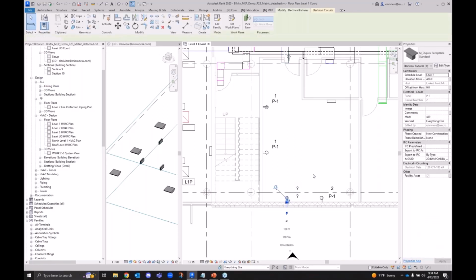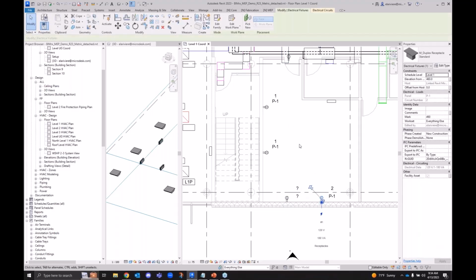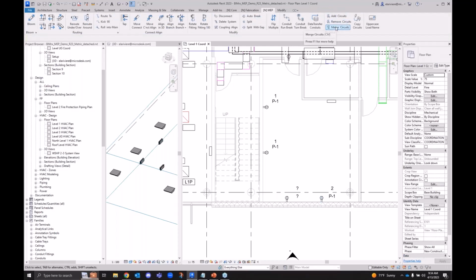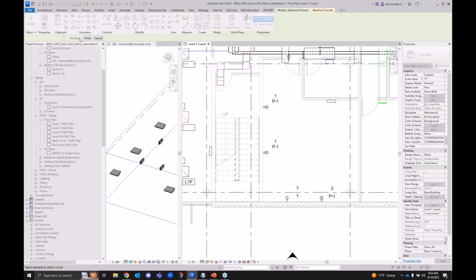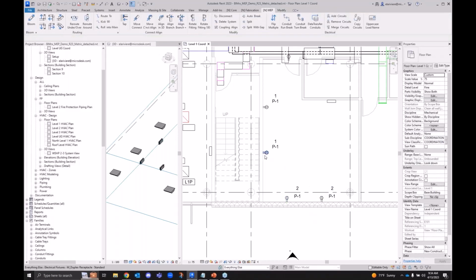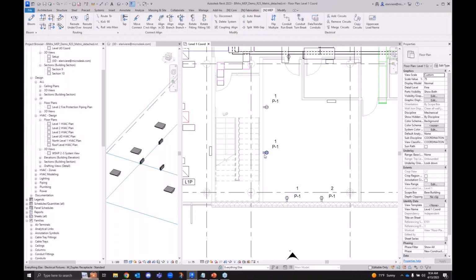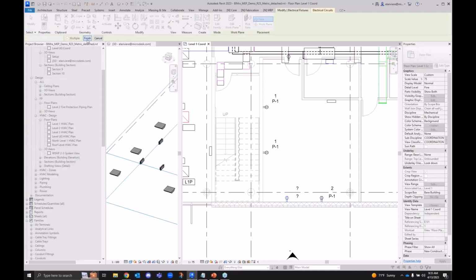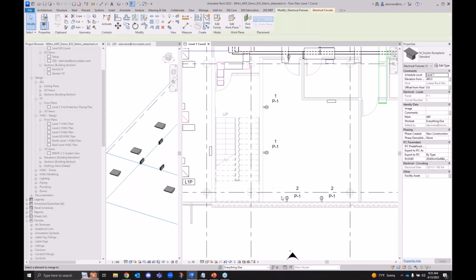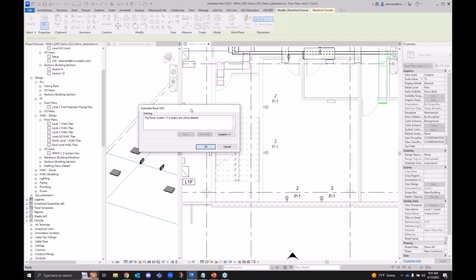So if I want to just remove something from a circuit, I can just remove it from a circuit. I'm using keyboard shortcuts, by the way, crew. This is all these add, remove, and merge, all keyboard shortcutted. If I want to add something back to this one, we could say circuit add, finish, adds it back to that one. Maybe I want to move that to circuit 1 instead. It's now on circuit 1. Maybe we want to remove it again. We can remove it again. Let's add it back to circuit 2, and then maybe we decide that we want to merge circuit 1 and circuit 2 together. Well, we can run a circuit merge, choose both of them, and we'll find that everything is now on circuit 2. Now, to be clear, I don't want them merged.